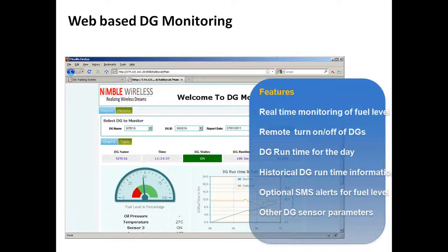monitoring device. And this remote monitoring device is actually working on a cellular network, and it transmits the data over the internet. It comes back to a central monitoring server or station. This remote monitoring device would be operating on a SIM card, which operates on a GPRS network. It could also have SMS capability if you want to do diagnostics information.